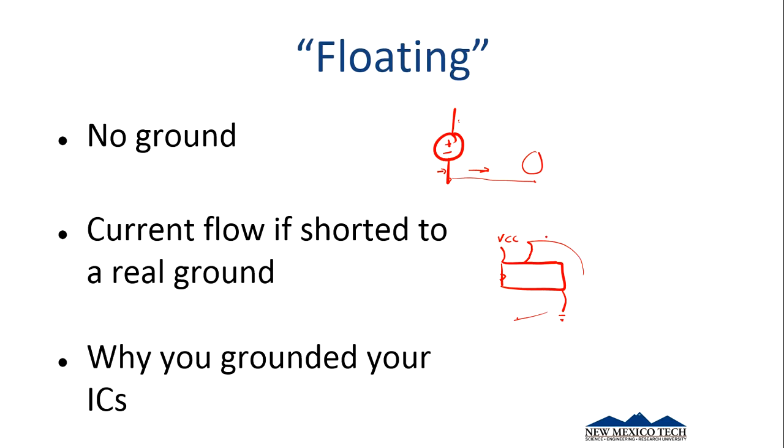While it was in between there, it was unpredictable what was going to happen, whether it treated it as a digital 1 or a digital 0. The reason for that is because you made that input floating. Because we don't know what's actually happening in here, it's basically a floating point. So that's also why, if you were building this and you didn't put in the ground wire, it didn't work right. It's because we had this floating point, and that's why I had you go and ground them.